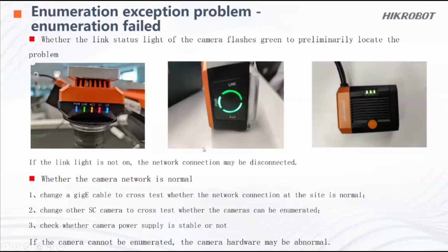So if the RJ45 interface is not working, then even if you change a GigE cable, it will also not work. So it is very easy to judge whether the port is damaged or not. For the second step, you can also change to another smart camera if you have one. Then you can also cross-test whether the camera has an issue or not.